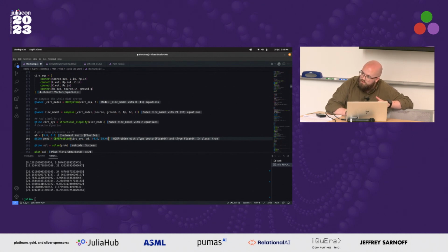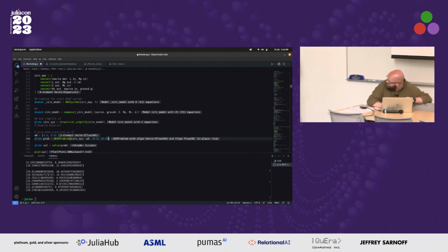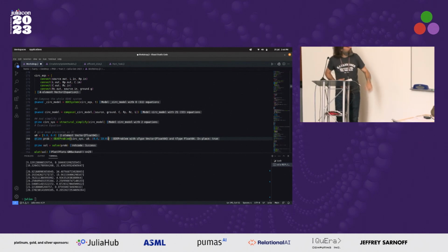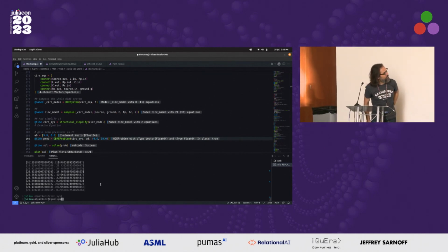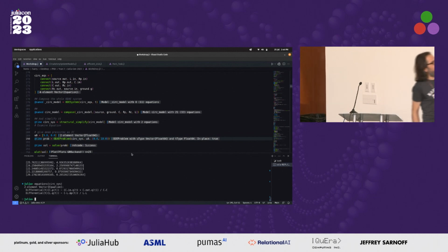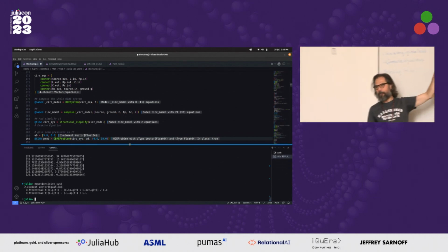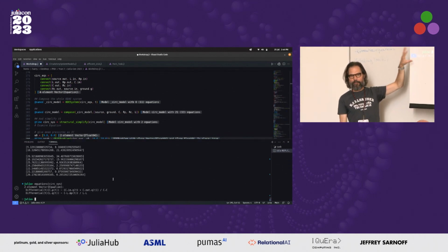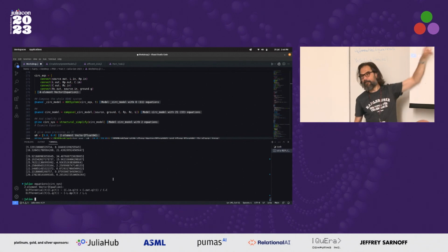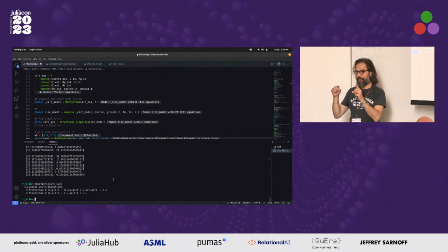One thing that I think is interesting at that point, and might have been lost for some, if you just bring the equations up again. You don't really know which equations ModelingToolkit is going to kick out for you. So it's always needed that you check the equations, so you know which boundary conditions, which initial conditions you need to define.